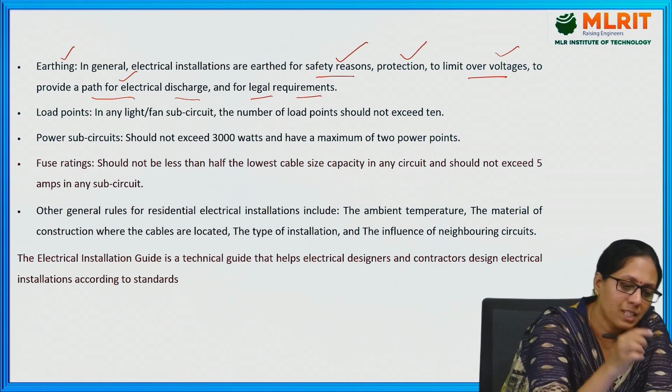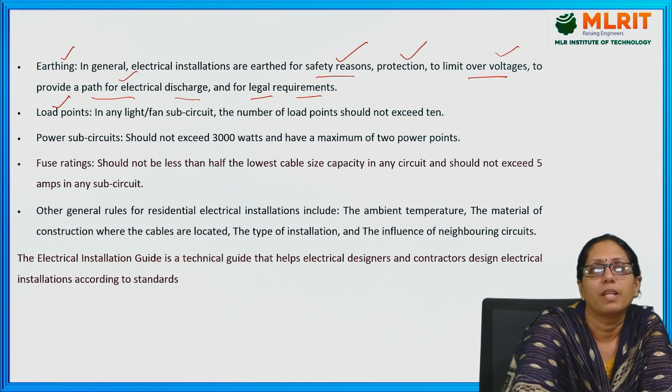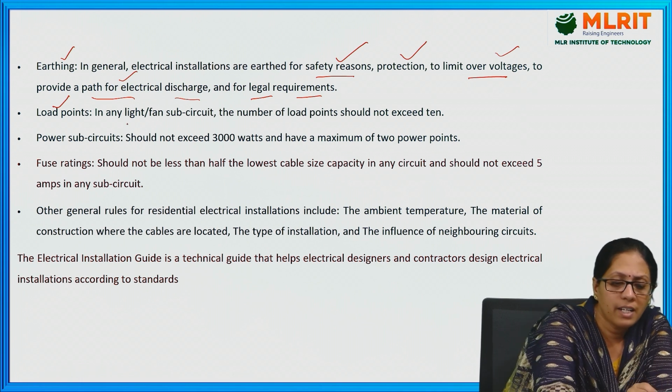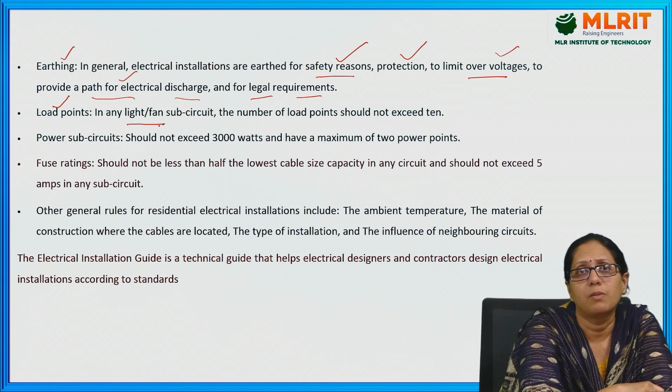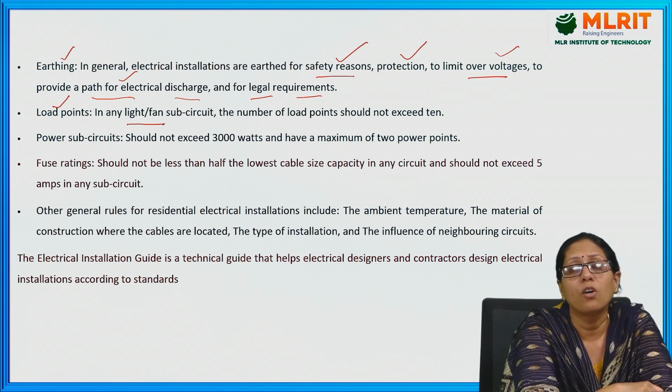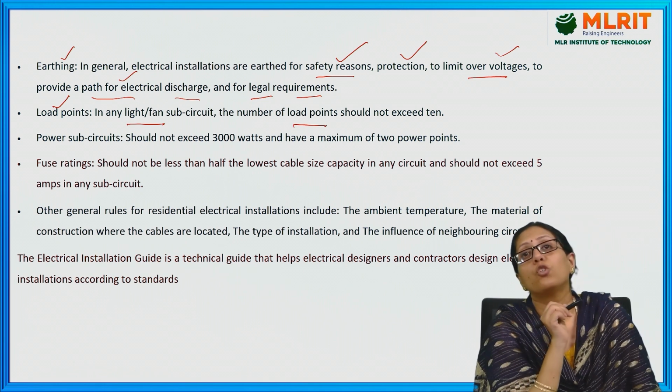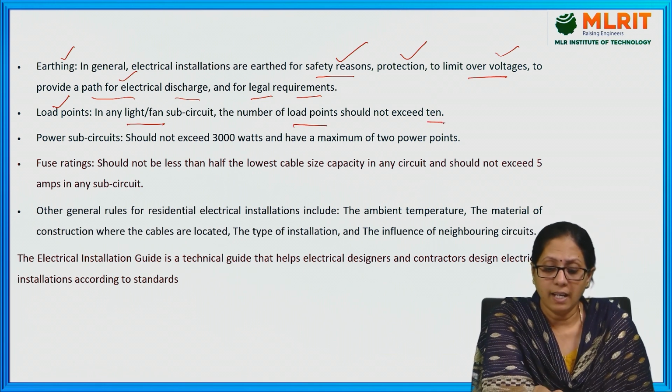The next point is load points. In any light or fan sub-circuit, the number of load points should not exceed 10.